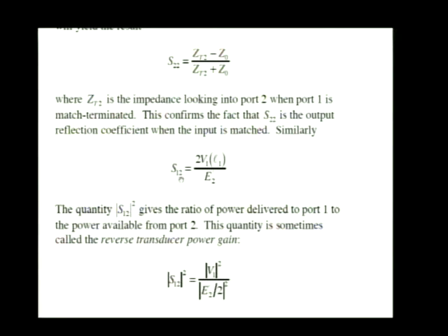The circuit that you use in order to compute S12 is the dual circuit that we used when we were talking about S21. Remember when we were talking about S21, we put a matched source on port 1 and a matched load on port 2. Now I guess we'd be putting a matched source on port 2 and a matched load on port 1, replacing 1's by 2's and 2's by 1's to be able to use this idea of duality.